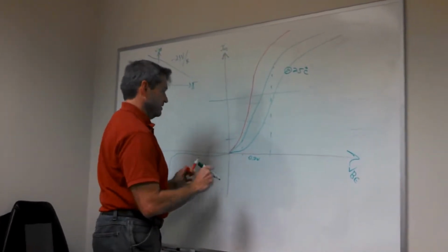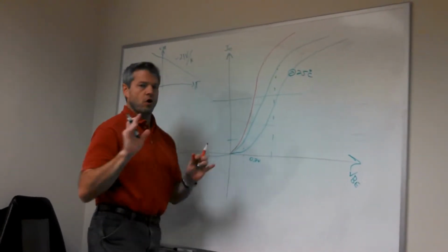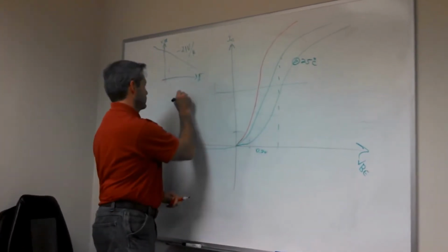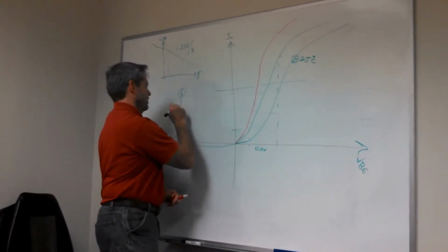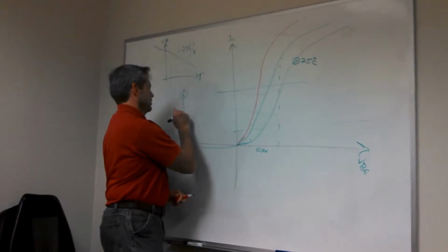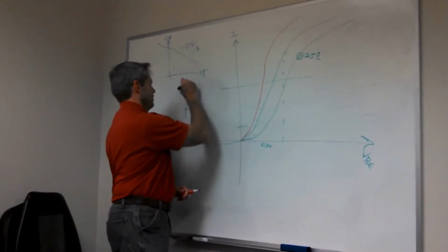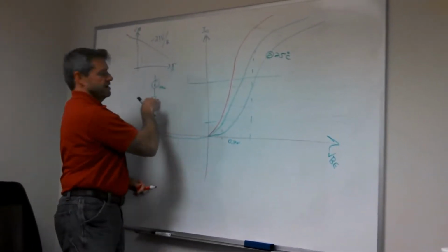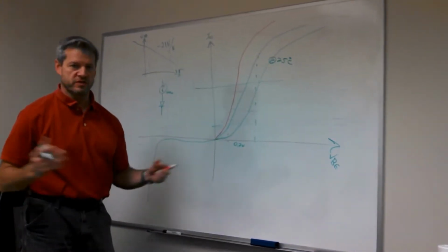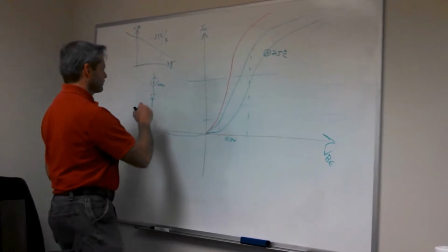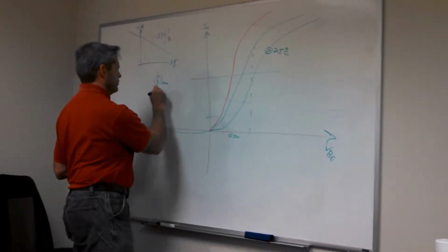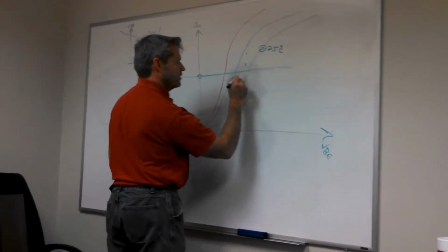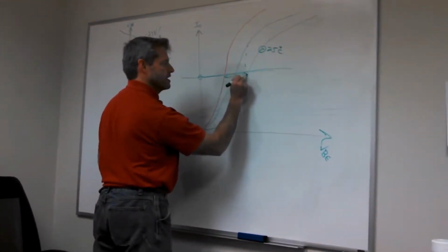So if you hold current steady, with a current source going into your diode that limits things to 500 microamps, you're always going to have 500 microamps going through there. That's what a current source does, right? Then you're holding it stable here, and what you're doing is sliding this curve back.